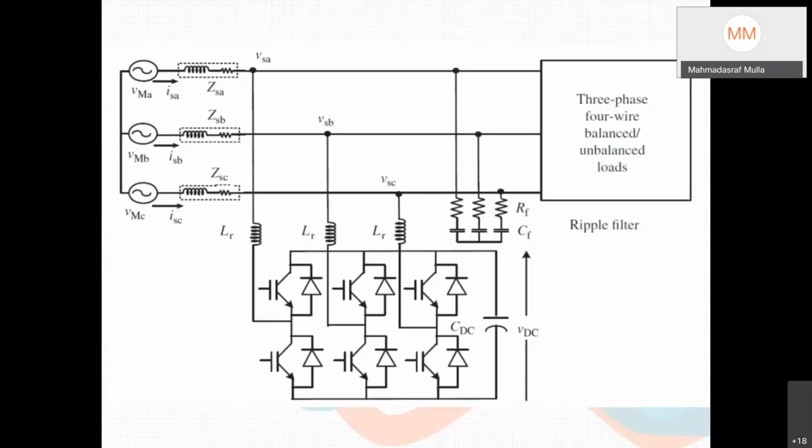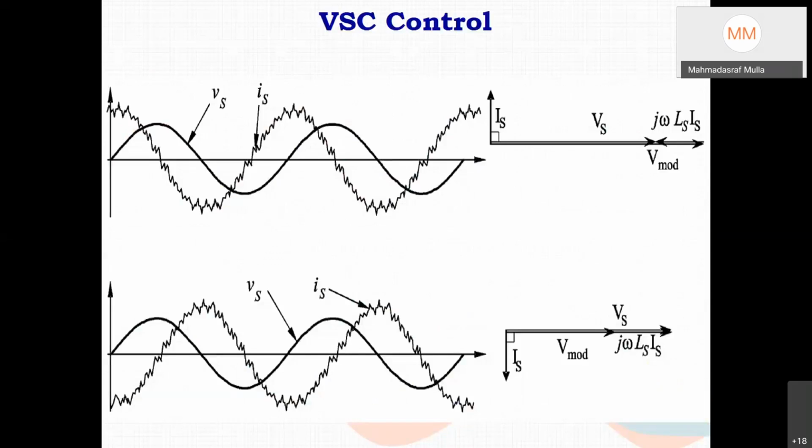Now I don't require a 100 kVAr capacitor or a 100 kVAr reactor. I take a small inductor, and at high frequency I control these IGBTs and the current through this inductor to follow the lagging or leading current, based on the magnitude of voltage I generate at the midpoint of each leg. So this is the operation of a VSC-based shunt compensator. Any question at this instant?